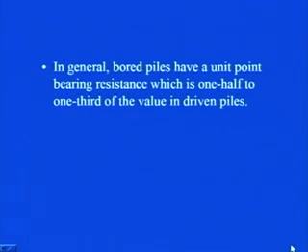In general, bored piles have a unit point bearing resistance which is 1/2 to 1/3 of the value in driven piles. So, let us say that you have found out the capacity under compression of a pile in case of driven piles. If you work out for bored piles, just to provide a check on what should be the order of this, this just gives you a rough guideline.